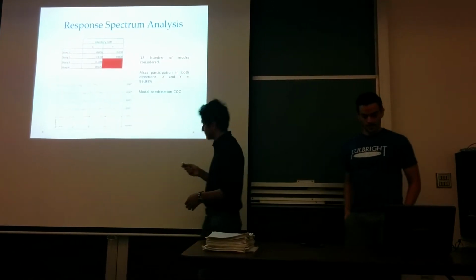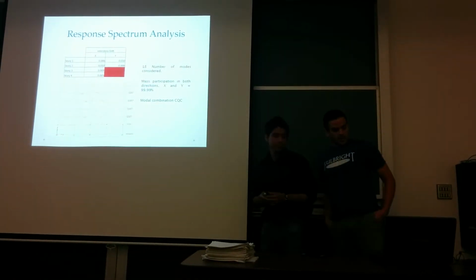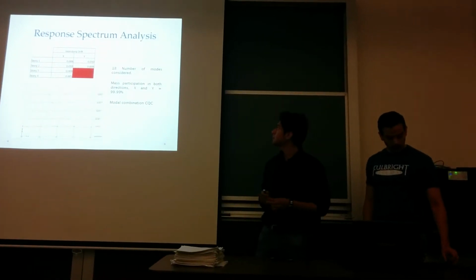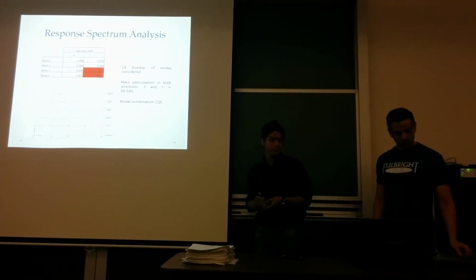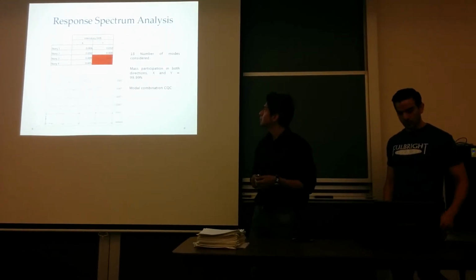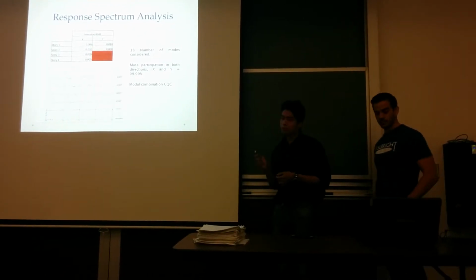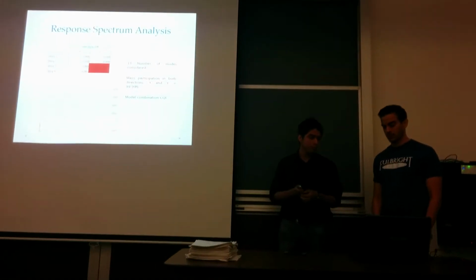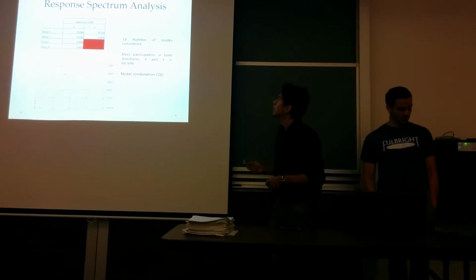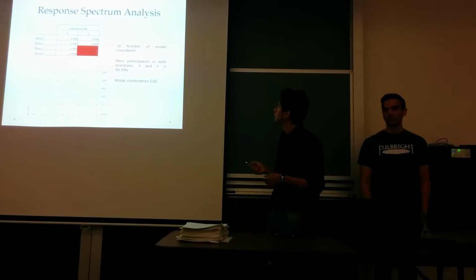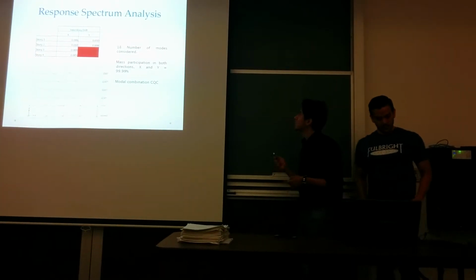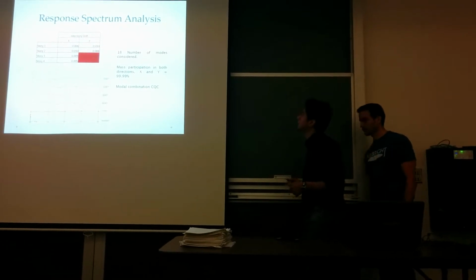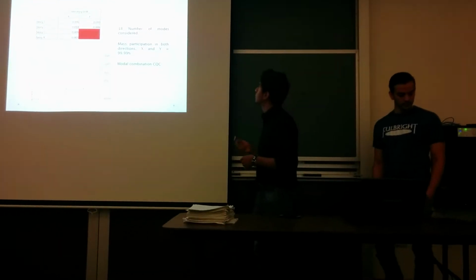In order to make sure that the structure needed to be retrofitted, people from Ecuador did just response spectrum analysis, elastic analysis, but we didn't have that, so we redid that in order to make sure about the answer that they had. So we decided to use 18 modes, and we completed the mass participation in both directions, almost 100%, and we considered the modal combinations as stated in the Ecuadorian code.